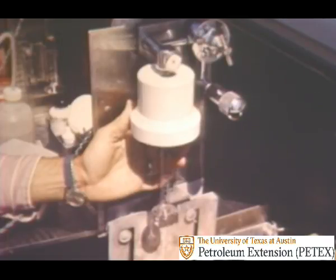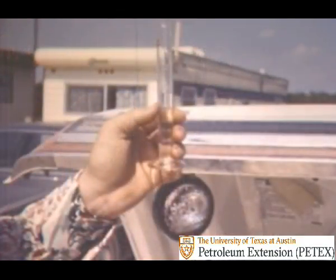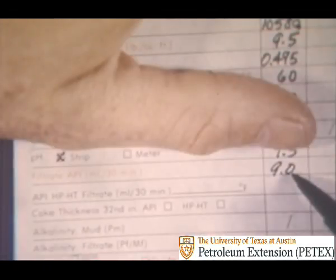Filtration rate gives an indication of the amount of filtrate lost to downhole formations and the amount of solids or wall cake build up on the wall of the hole. The amount of filtrate in milliliters is noted and is recorded on the form. In this case, it is 9.0 milliliters per 30 minutes.